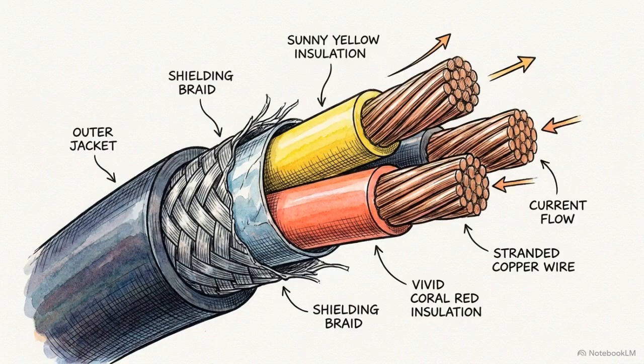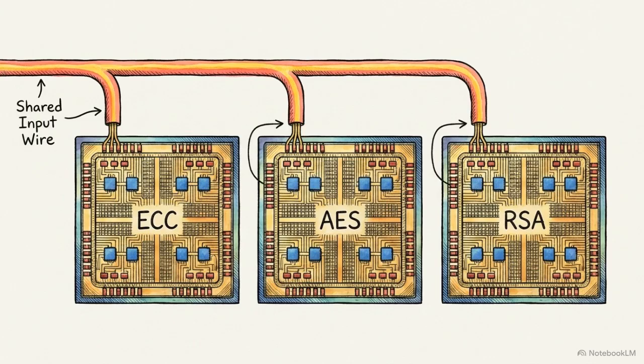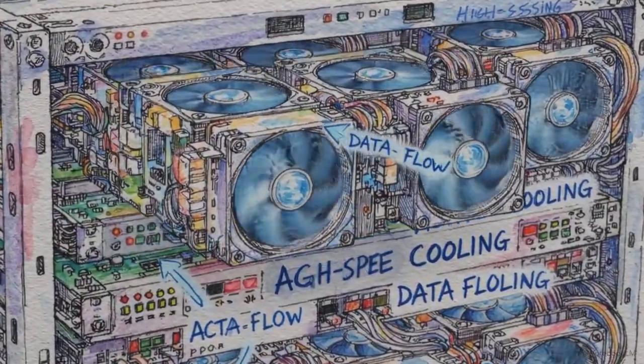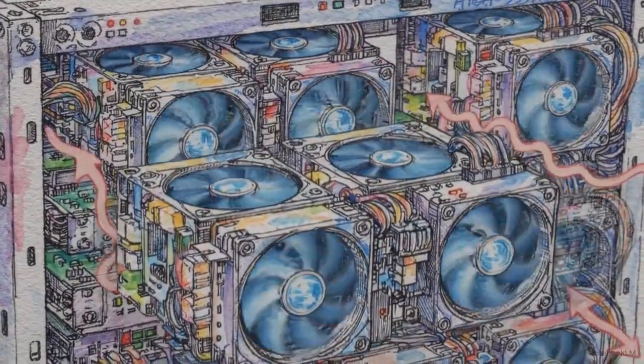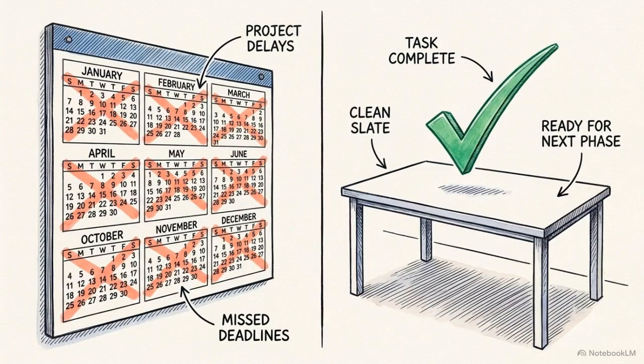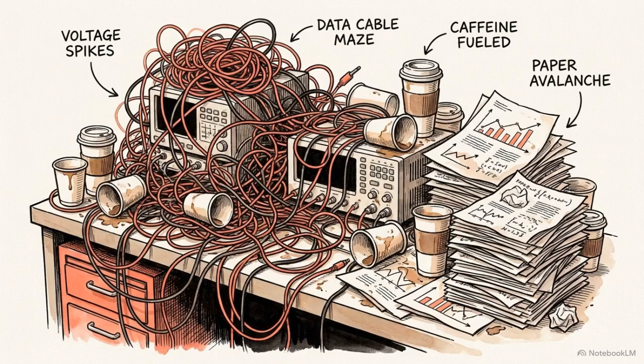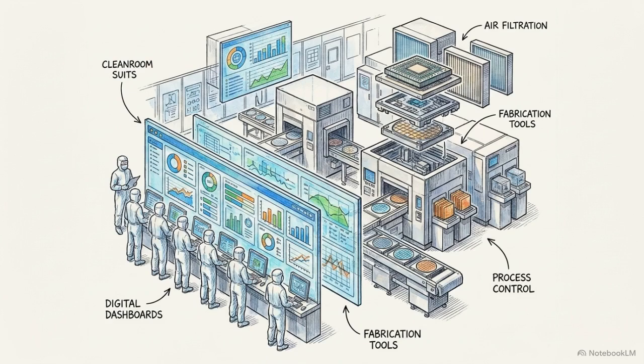Because GPAM targets the physical reality of the power trace, its architecture generalizes to entirely different algorithms, attacking software-protected AES datasets with 0 structural changes. Adapting this model to evaluate a new chip requires only a few days of automated hyperparameter tuning on standard GPUs, replacing months of expensive manual trace curation by side-channel experts. By automating the pipeline from raw oscilloscope capture to key recovery, generalized models transition side-channel evaluation from a specialized research endeavor into a routine, automated software testing process for the semiconductor industry.